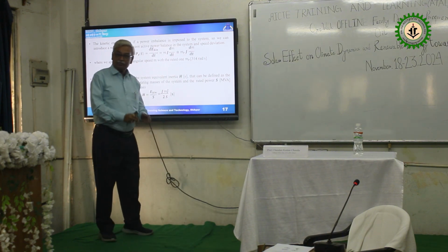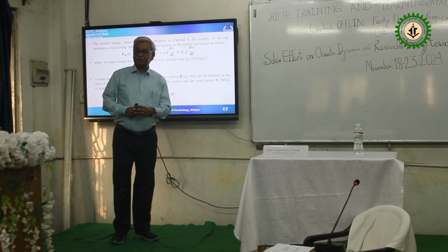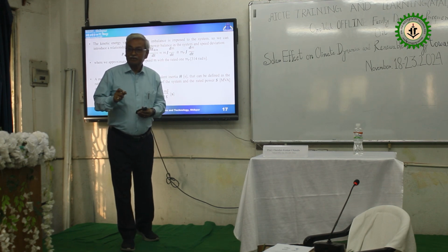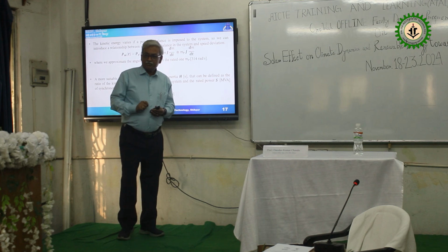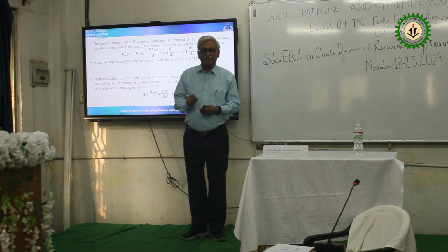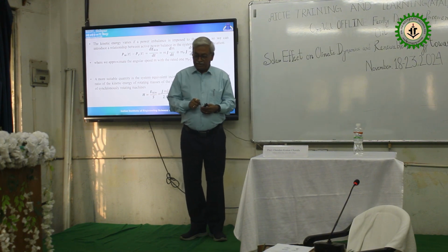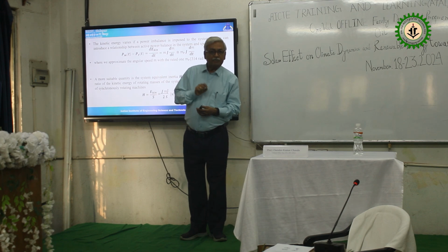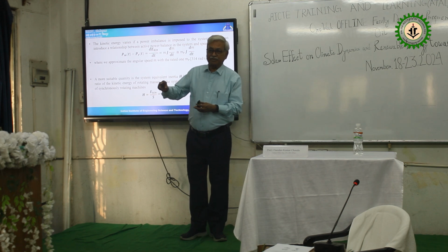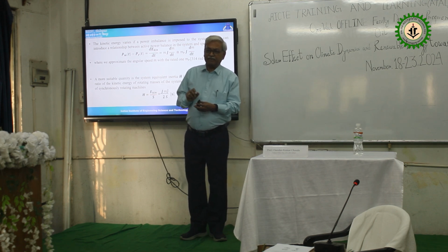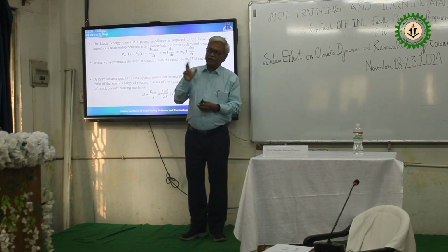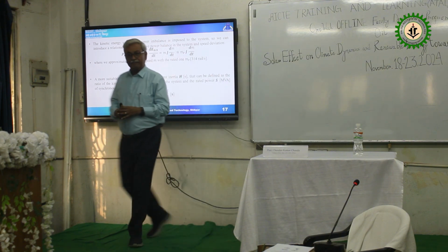So that's the thing with the generator also. As far as rating and specification are concerned they are the same, but characteristically the inertia values are mashed up, which is very difficult. So what to do? Instead of going into individual machines, which is tedious mathematically and also tedious for a computer, we get the mean value. We get the inertia of different machines, go with little assumptions and take the average value. We define H in such a way that it will finally satisfy our calculation.